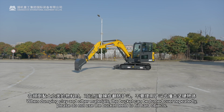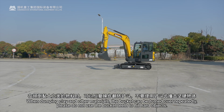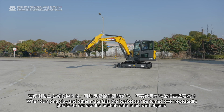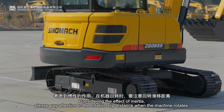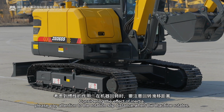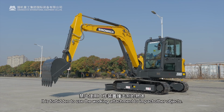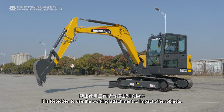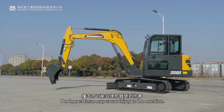When dumping clay and other materials, the bucket can be turned over repeatedly. Please do not use the bucket teeth to hit hard objects. Considering the effect of inertia, please pay attention to the rotation slip distance when the machine rotates. It is forbidden to use the working attachment to impact other objects. The impact force may cause injury to the machine.